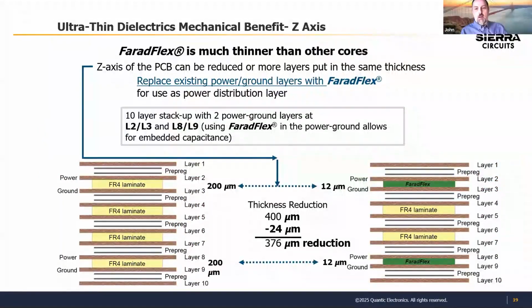The nice thing also about embedded capacitors is their thicknesses. You can buy the old 2 mil, what we call the ZBC 2000, it used to be called BC 2000, and a lot of people use that. It's just the 2 mil fiberglass. You get some good performance out of that versus a thicker core, but the benefits really start to pick up when you're talking about 1 mil and below.